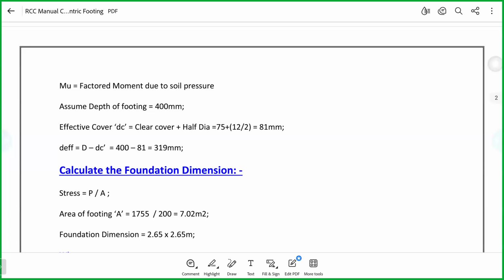This is you're talking about the reinforcement things. Okay. The reason why you are providing reinforcement is to resist the moment, to resist the tension, because concrete is strong in compression, weak in tension. That's the only reason we are providing the reinforcement, isn't it?